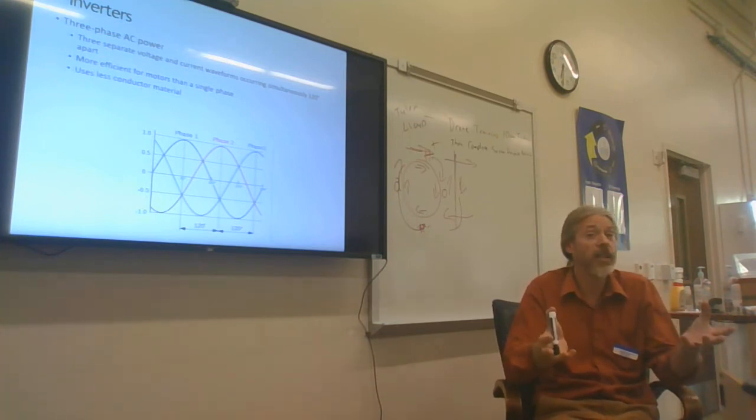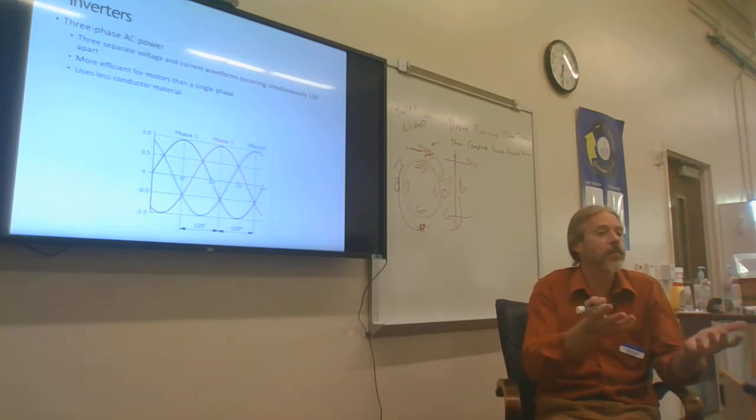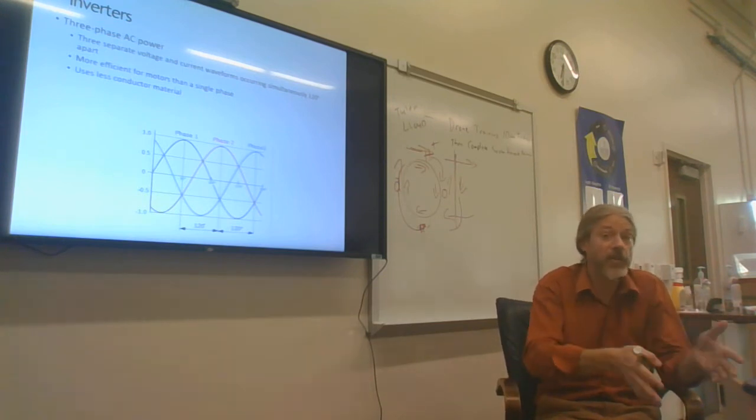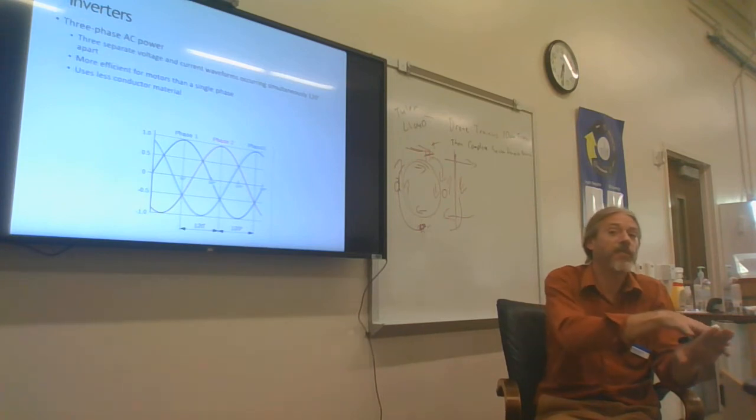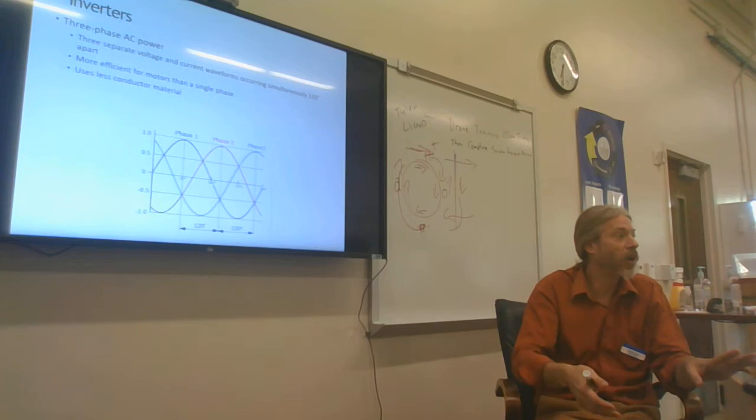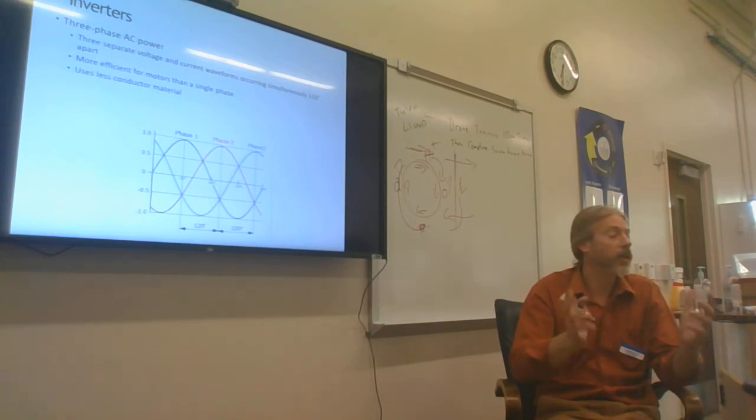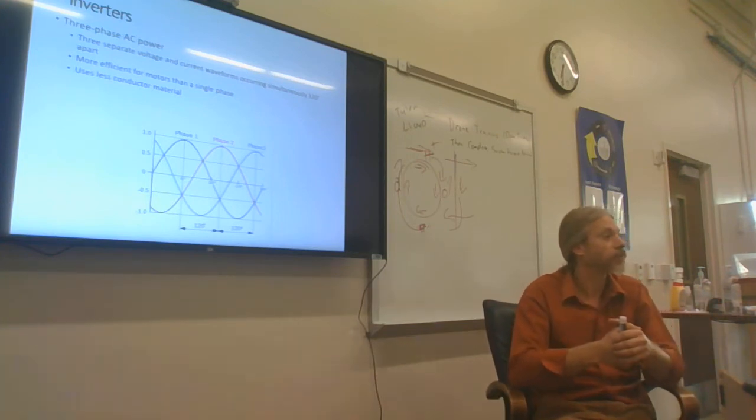A lot of people get intimidated, like, oh, it's 3-phase, I don't know how to wire it. They don't even have you label which phase is what. It's just hot wire, hot wire, hot wire, neutral wire, ground wire, monitoring, and that's it. But you can't have a 3-phase inverter if you don't have a 3-phase grid. Yep, and out in the country, most of the time.